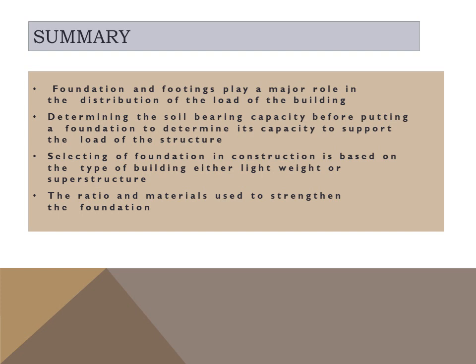So to sum up, foundation and footings play the major role in the distribution of the load of the building. Determine the soil bearing capacity before putting in a foundation to determine its capacity to support the load of the structure. Selecting a foundation in construction is based on the type of building, either lightweight or superstructure, the soil, and the materials used to strengthen the foundation.